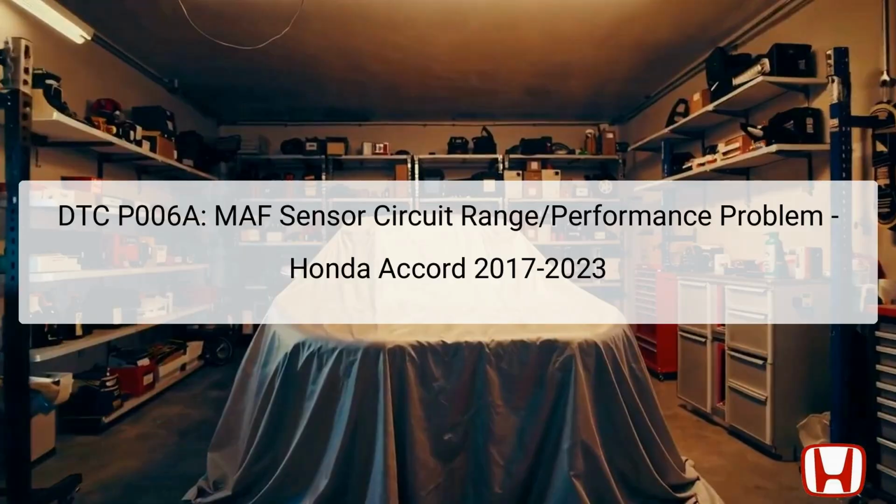The DTC P006A indicates a problem with the MAF sensor circuit's range or performance in the Honda Accord models from 2017 to 2023. The mass airflow (MAF) sensor measures the amount of air entering the engine and helps the engine control module, ECM, adjust the fuel-to-air mixture for optimal performance.